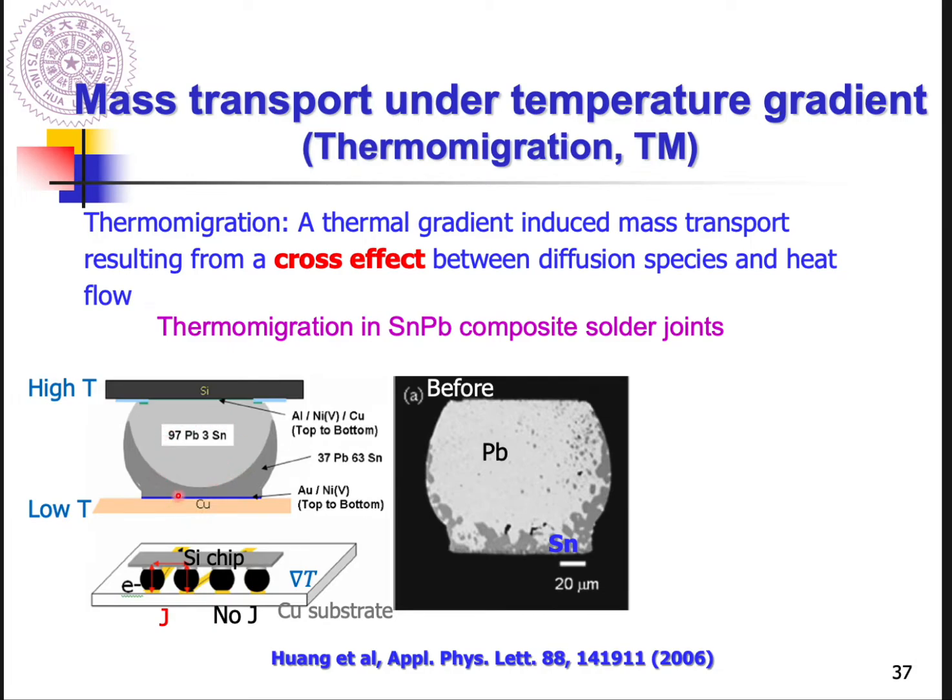is in order to what? In order to have a lower fabrication temperature to fabricate this solder bump, but this solder bump finally will sustain higher working temperature. So the upper region is designed as a lead-rich region, which can sustain higher working temperature. So this is how people design this kind of geometry or composition distribution of this lead-tin alloy.